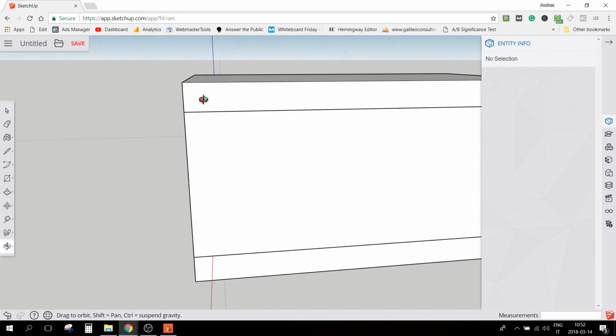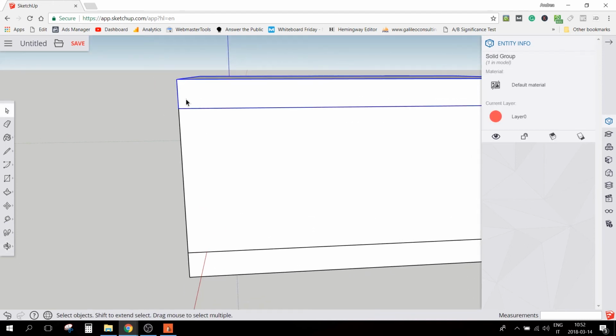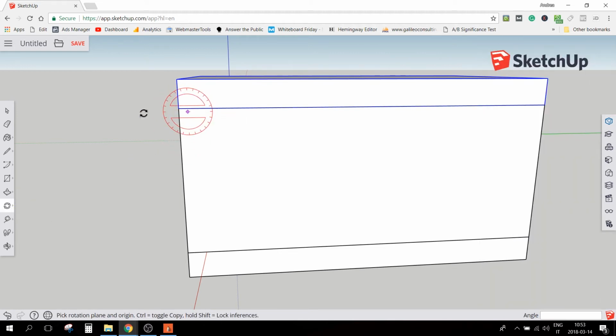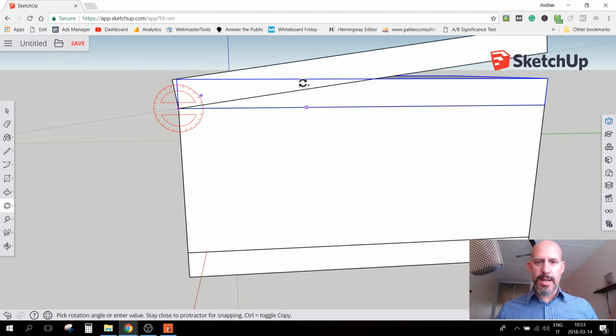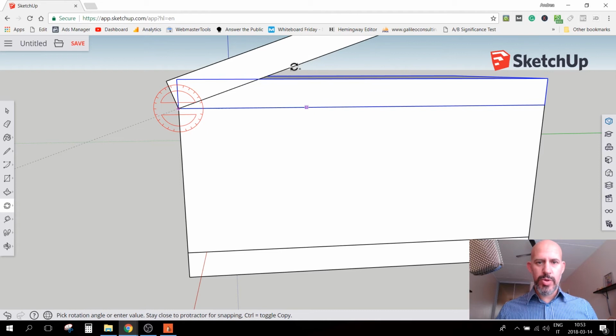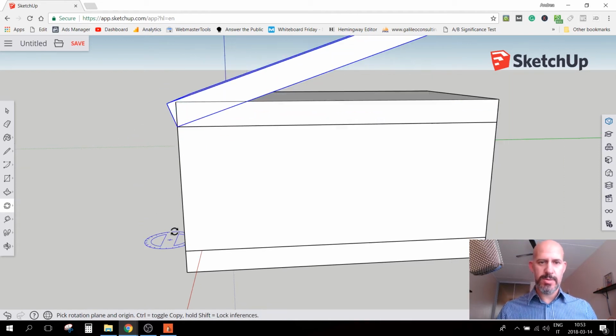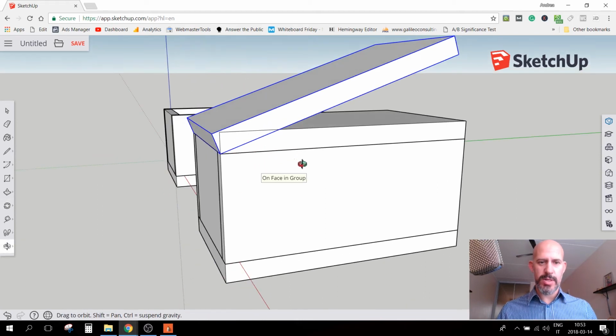now if we give it some angle, let's select it, let's pick this rotate, and you gotta snap it in the right place. Yes, and then you just pick up a point on the solid and snap it, and now you just push it up, and you can type 20, and this will just put the roof at an angle of 20.